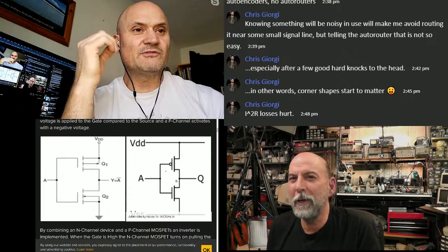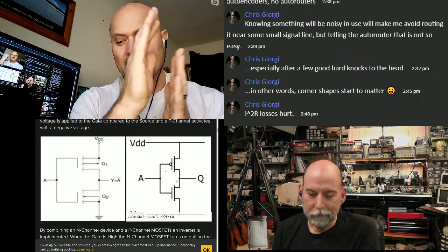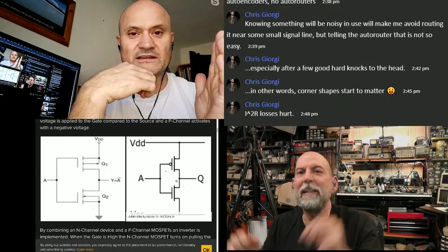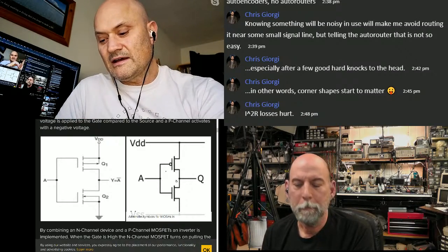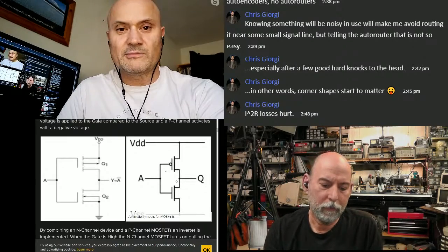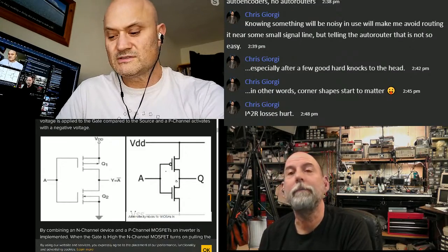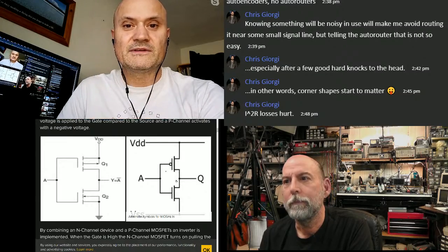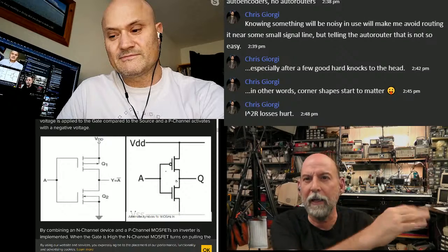If you have nice polished copper, say, and you smear epoxy resin on it and let it dry, you can peel it off really easy. Delaminate it right out. So these boards would delaminate without that chemical etching process that oxidizes the surface of the copper and makes it rough. But then you get return path current losses because of the skin effect. You're forcing the current through the surface, and that's rough. And it's following the peaks and the valleys. Yes.